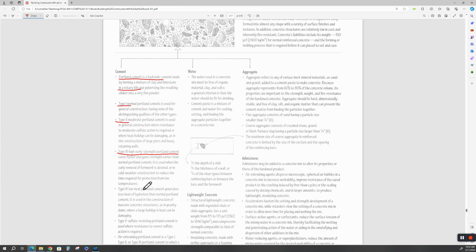We'll get into that in a little bit, but you have a 7-day strength and a 28-day strength. Samples are taken at the site of the pour, just round cylinders of concrete. They're saved for the 7-day break, and then for a 28-day break. The testing lab takes them back, puts them in a steam room, lets them cure, and they'll do a 7-day break and give you a report, and then they'll do a 28-day break and give you a report.